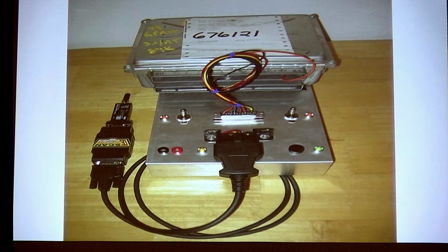Their own flavor says that I've got to backwards engineer it. I take this box right here, and the only wires that I've got into that box are power, ground, and comm wires. That is it. To talk to these modules so I can backwards engineer them, I plug them into this box, I power them, and then we start banging on it until we can communicate with it, and we figure out our timing sequences for the different cars.